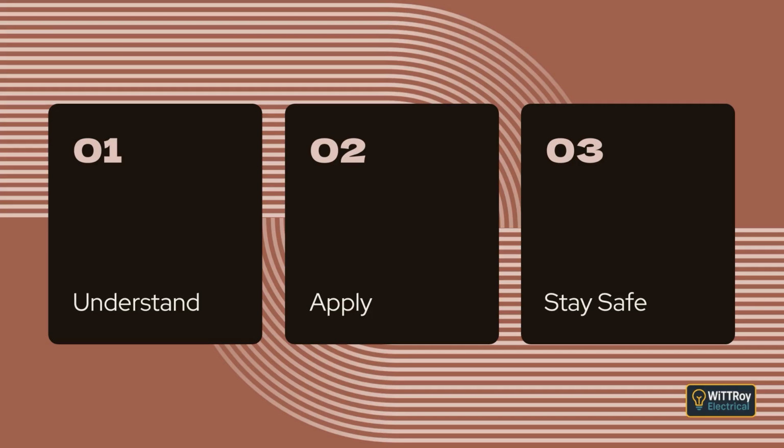Some electrical installations may be sensitive to electromagnetic interference created by current in nearby cables. Interference may be reduced by selecting cables with low magnetic emissions, installing cables in enclosures that shield magnetic fields, or arranging cables in configurations that minimize magnetic field strength. Clause 3.10 Enclosure of cables. This clause explains when cables must be enclosed in a wiring enclosure, what types may be used, and how they must be installed. Clause 3.10.1 General.